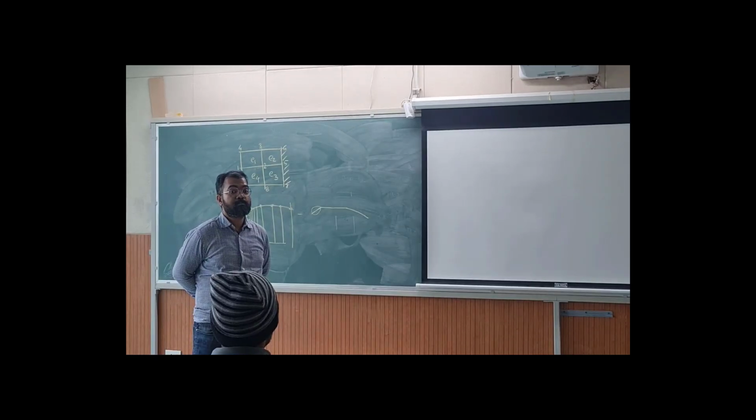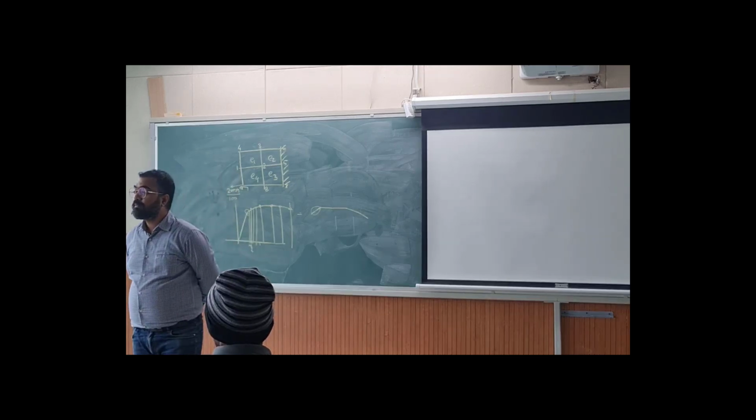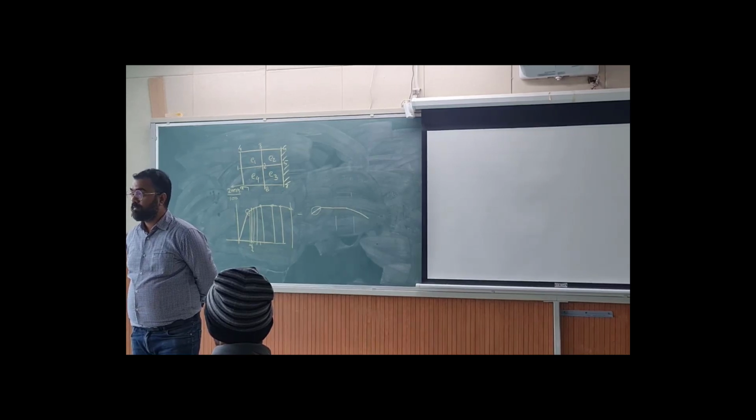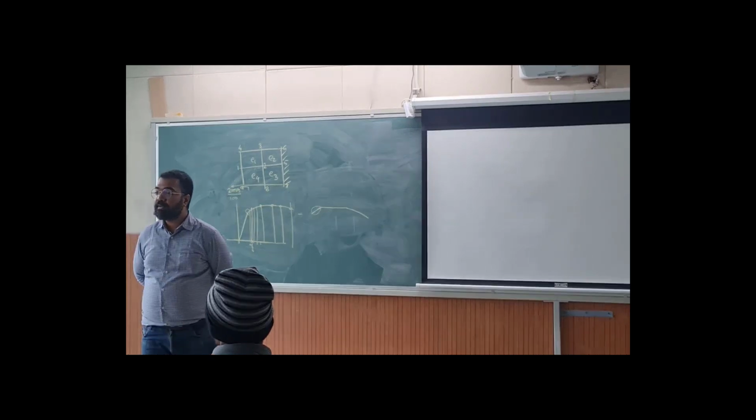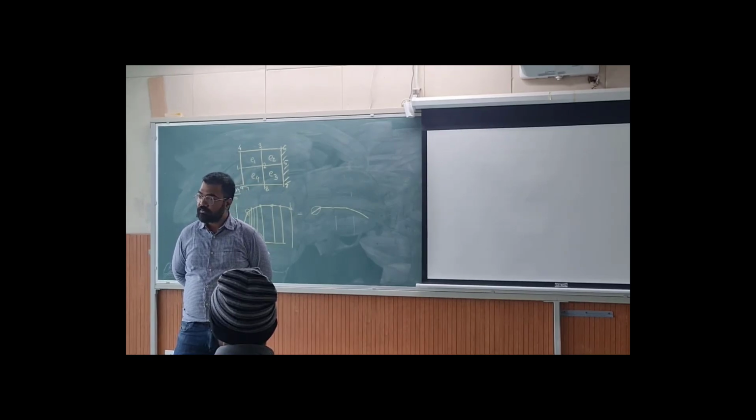We will have to reduce the elements. How will we reduce the elements? Then you will lose on accuracy. You have said that to get accuracy, we can do two things. One, we can add more elements. Yeah, H refinement, P refinement, that you can do. But in both cases, the stiffness matrix will have more values.